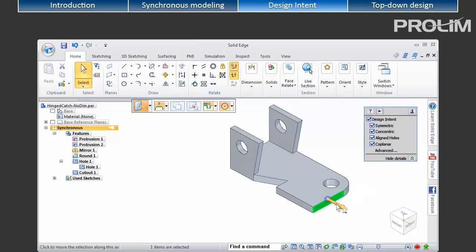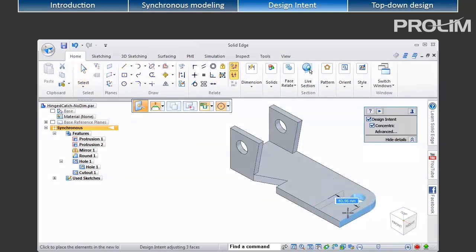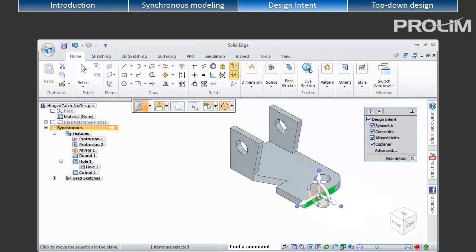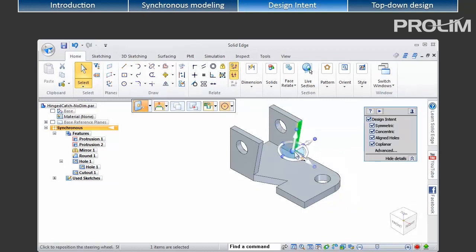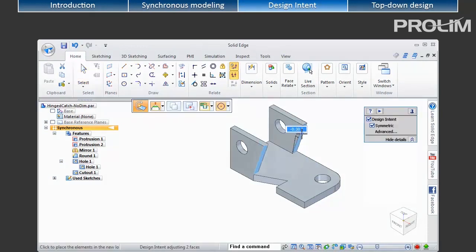We can get the same predictable results by pulling the outer face. Other CAD systems don't allow such edits because holes are driven from other features. As we make changes, including rotations, any rounds are automatically updated, and any blend patches, that blend intersections, are maintained.